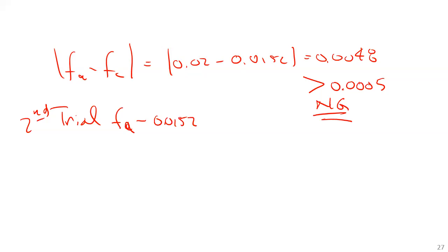And again, you would find that you achieved about the same discharge we found when we combined the Swamee and Jain equation with the Darcy-Weisbach equation, a discharge of 0.202 cubic meters per second. So the trial and error solution isn't that bad once you set it up. Quite honestly, once you have the equations set up and you program them into a spreadsheet, it might take you a few minutes to program them, but then it takes you seconds to just go through it.